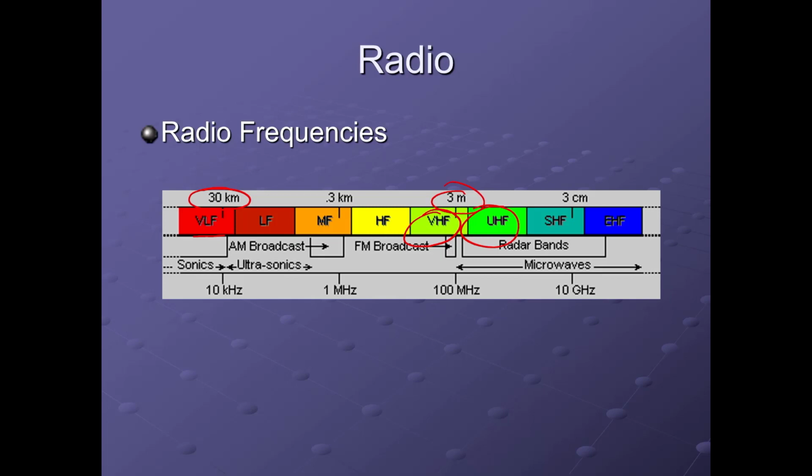And furthermore, the propagation through free space is different even between two bands. Let me give you an example. If you were looking at communicating with a tower up on a hill in Calgary, VHF would be a better means of communicating to the tower and over to somebody on the other side of the hill than UHF. That's because the free space losses on UHF are much higher than VHF.